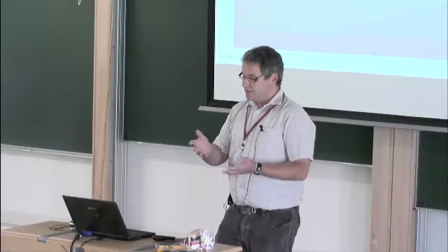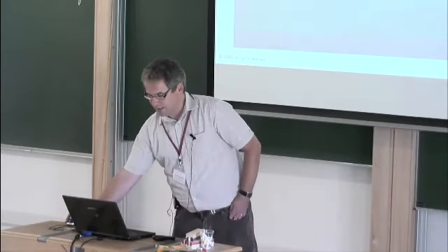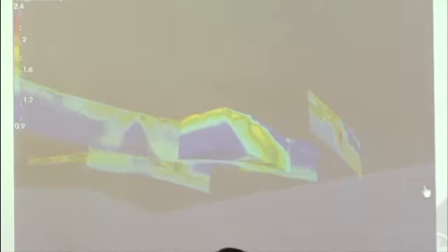So just before I go into the details, I'd like to show you the context of the resistivity images. This is the topographic surface at the landslide site, and the resistivity images are embedded in it. I'll just set this going in a couple of seconds, but you have these 2D images and a 3D imaging volume there. So let's set that in motion. The 2D images are from reconnaissance surveys that were done a few years ago. The 3D volume is alert data from the system.